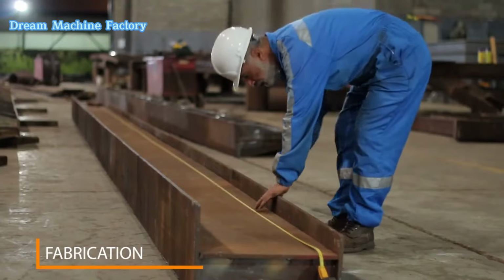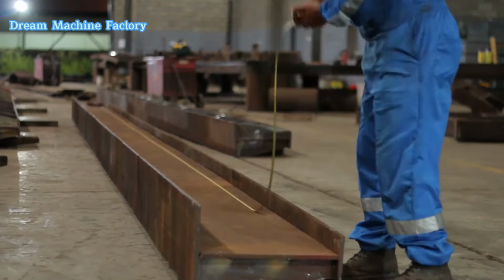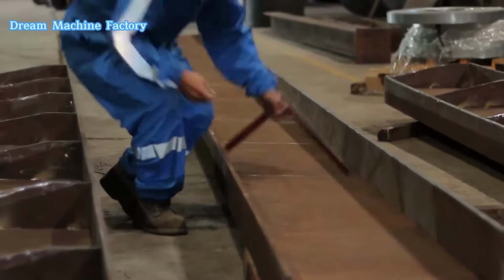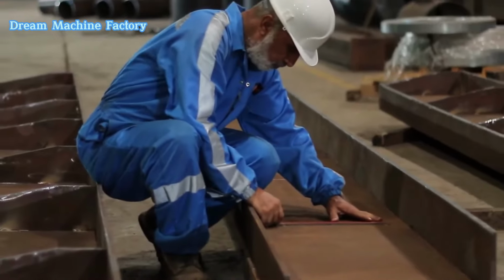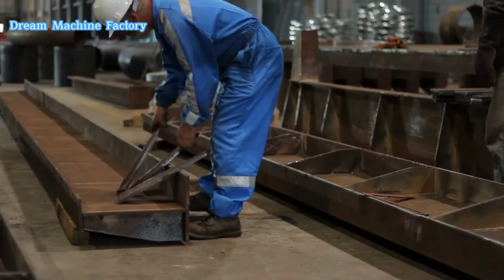Fabrication involves assembling the cut and ground steel pieces into the desired shape. This process includes bending, rolling, and drilling as needed. The components are temporarily held together using clamps or tack welding before final welding is done.